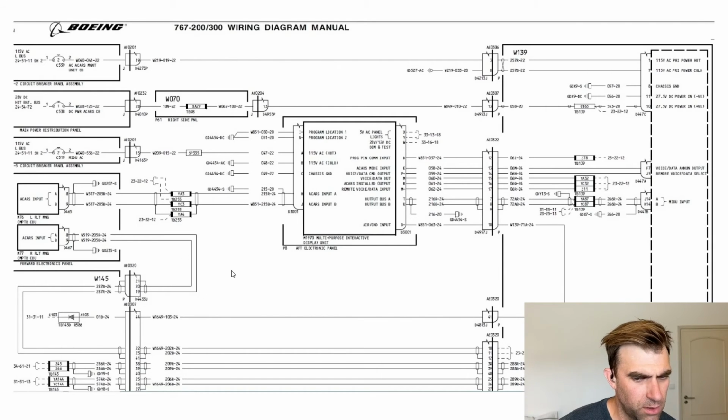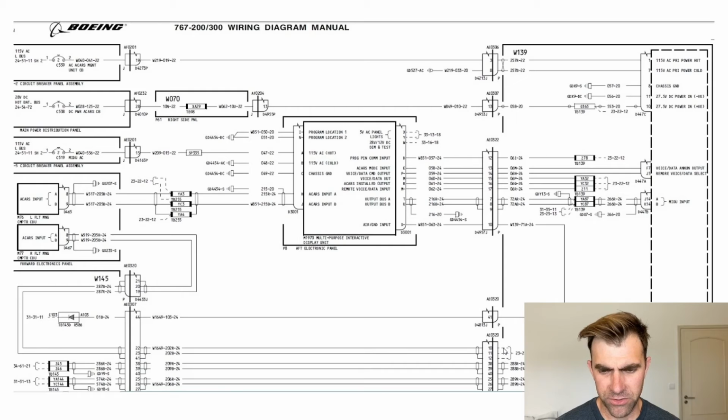See here. Another thing that you're going to see too are disconnects. Maybe it could be called a bulkhead disconnect. So you can see down here there isn't a component that connects to this connector, but it's just a female and male connector that are mounted on a bulkhead. And that's just to pass through maybe a firewall or a pressurized section of the aircraft, but it's still